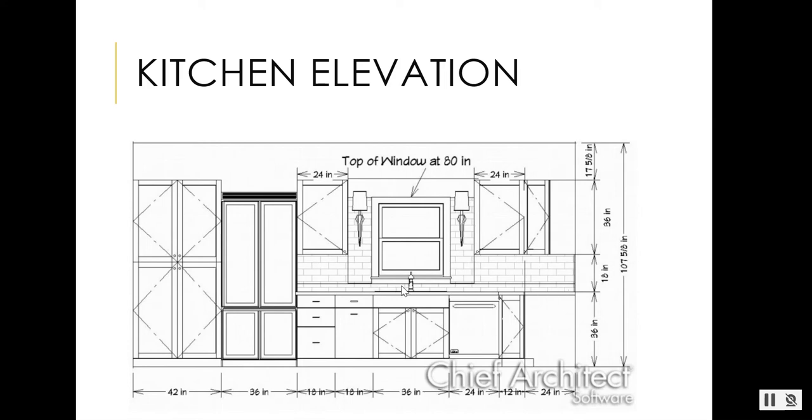So here you see kitchen is in inches. They've also created some nice details by adding this lighter subway brick pattern backsplash. They show the installer how far it goes up to the windowsill. They show some nice poles and some casework detailing. See, with the windowsill and the casework. Beautiful detail on the sconces. And so this is the kind of thing we want to see. They show some of the millwork around this pantry, like a shaker cabinet. And so that really shows you what the style is, and it gives a great design intent.